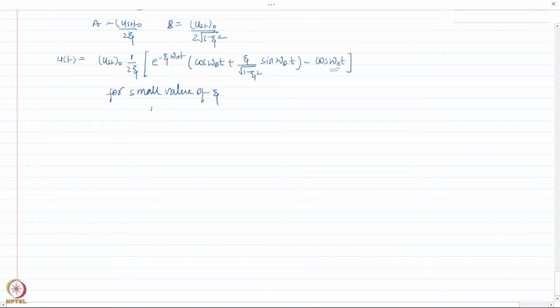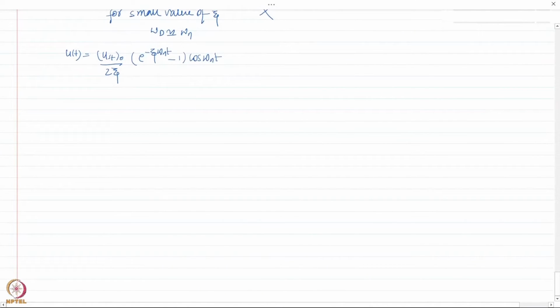So my omega_d would become omega_n. This term I can neglect, because it becomes very small and is multiplied by zeta for a small value of damping. So what I'm basically left with is u(t) as u_st0 divided by 2 zeta, and then here I would have this term into cos omega_n t.